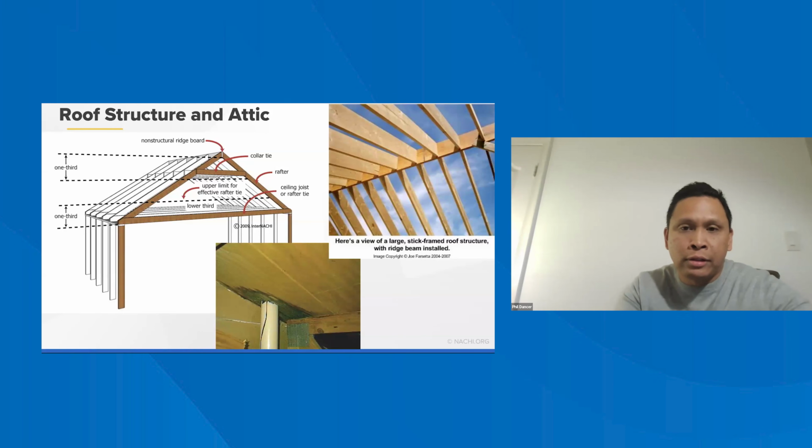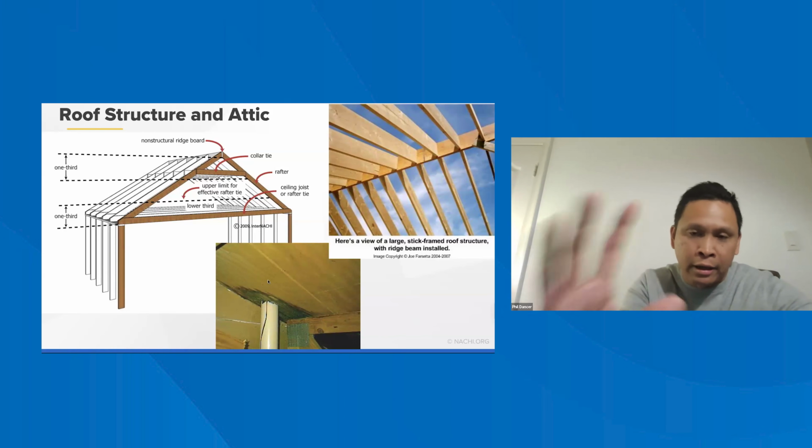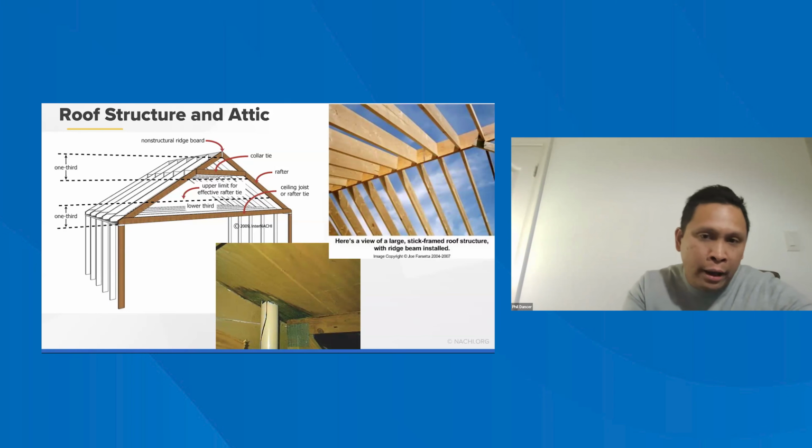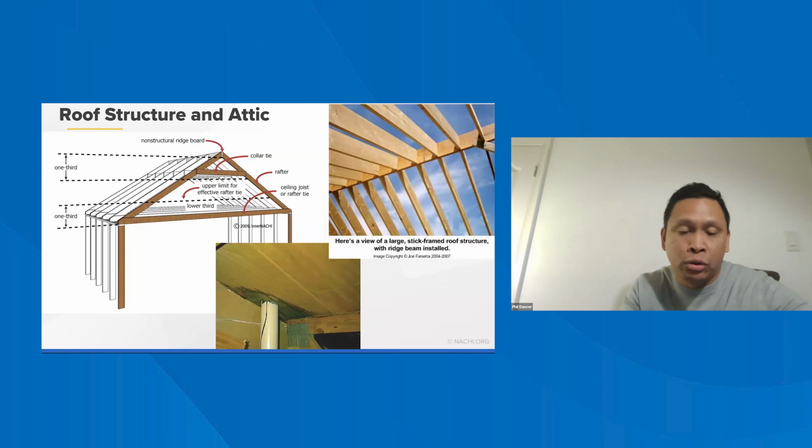Okay. So the other one that's also important, I think it's just important to talk about really quickly. See in the center picture there towards the middle, you'll see some water standing on the roof. This is more of a roofing condition, not a structural one, but it is important to know as much as you can. Try to make sure that all openings are properly flashed, right? So I see a PVC pipe there, so I am expecting to see a pipe boot on the roof.